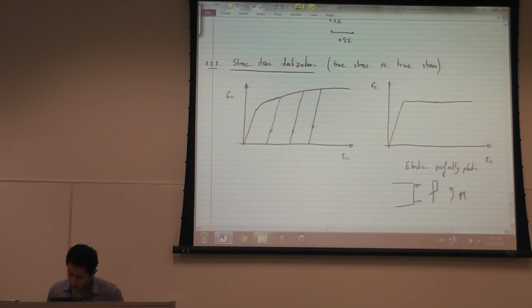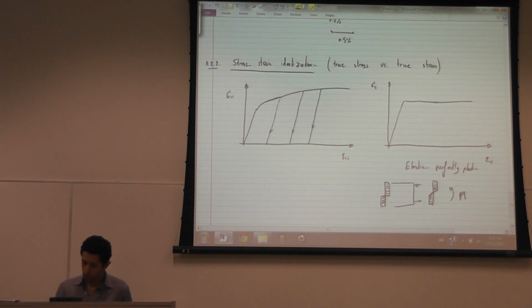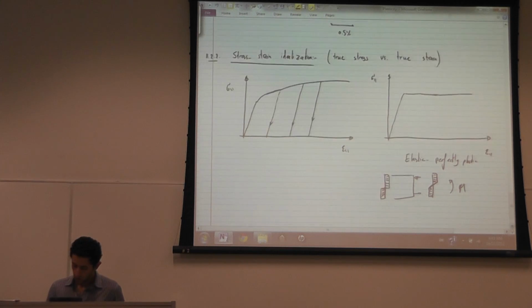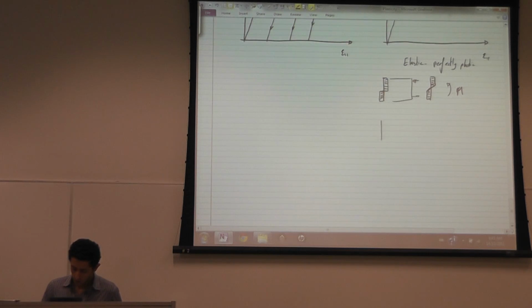You have a region of elasticity and everything else plastic, and this is much easier to calculate by hand. And in the limit, you get this block and this block. So it's much simpler to calculate the moment based on that rectangle rather than a curved surface. Another idealization.